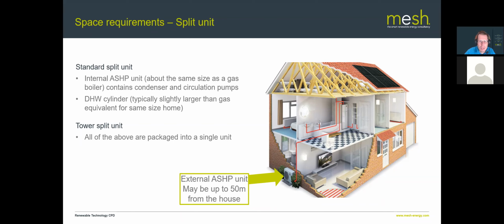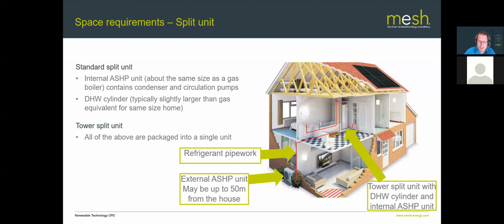People sort of tuck that evaporator unit well away from the house, or up on a roof or somewhere where it's really discreet. And here's our refrigerant pipe work. This does need an F-gas qualification to install. You can't just get your normal plumber to install this. They do have to have some specialist qualifications.